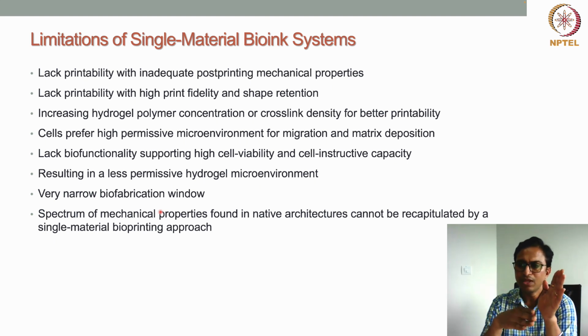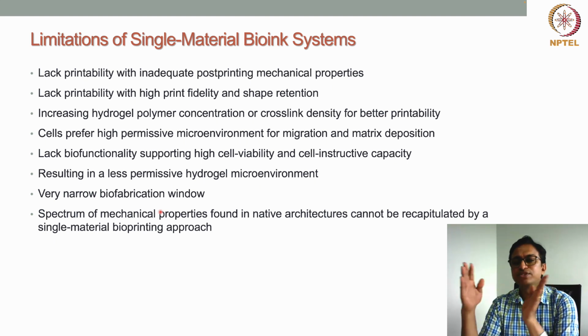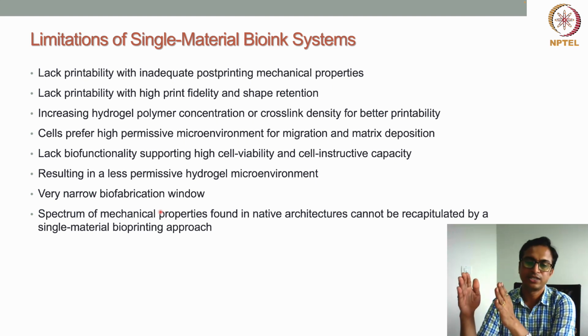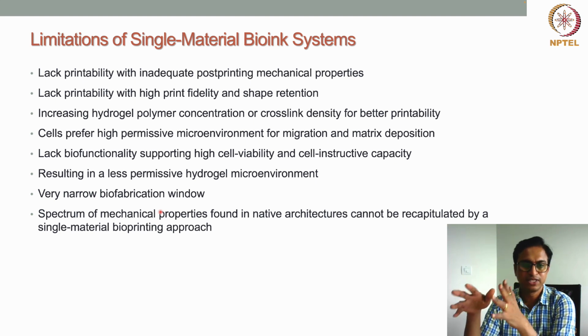On the other hand, if you increase the polymer concentration to a very high extent, the viscosity will increase, and due to the high viscosity, your printability will probably also improve. Print fidelity, post-print shape retention and mechanical properties can improve further.